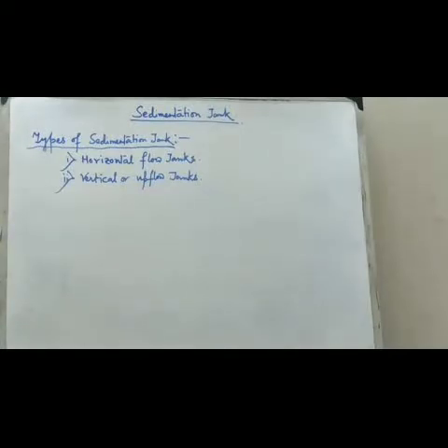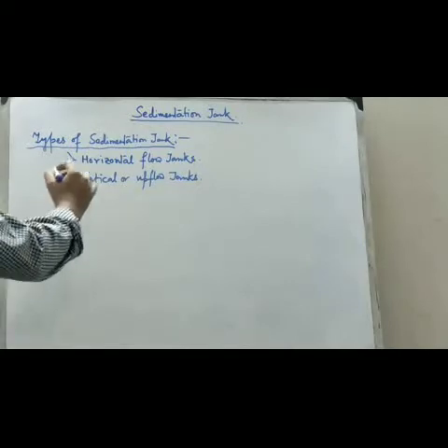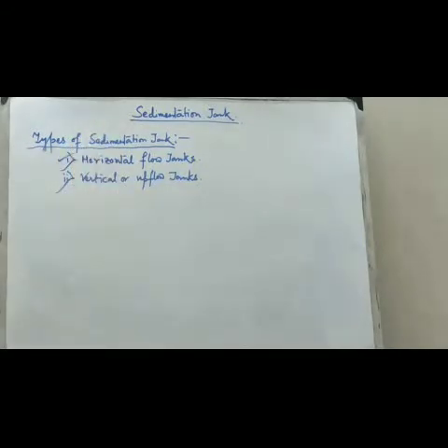In the design of horizontal flow tanks, our aim is to achieve as nearly as possible the ideal conditions of equal velocity to all the points lying on each vertical line in the settling zone.